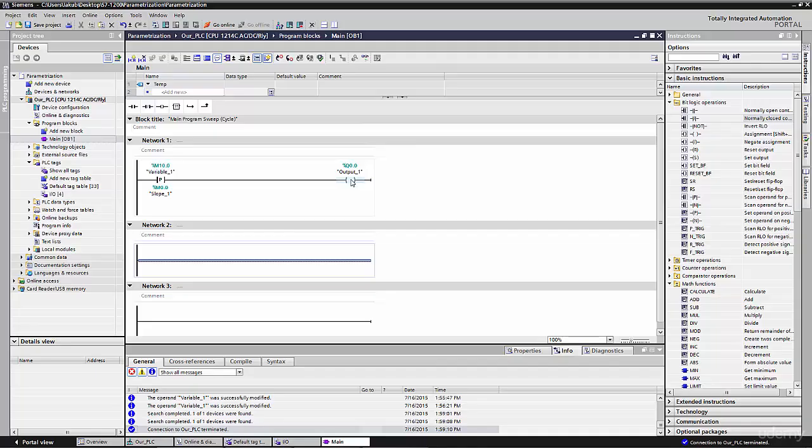Do you remember it was about 2 milliseconds? So our output will be switched on for only 1 millisecond. If we have, for example, a PLC with a relay output, the relay does not have enough time to switch on, so we cannot even check if everything is working.